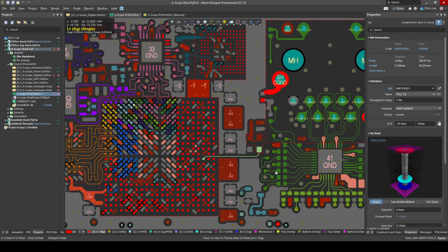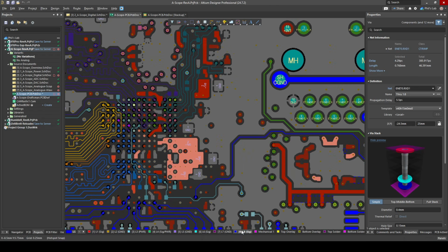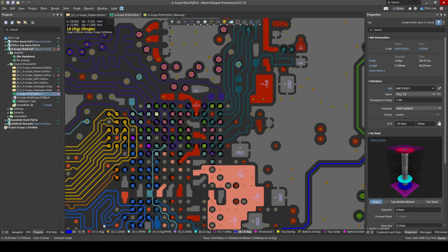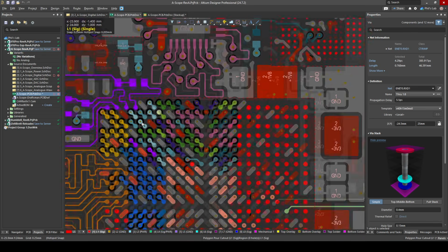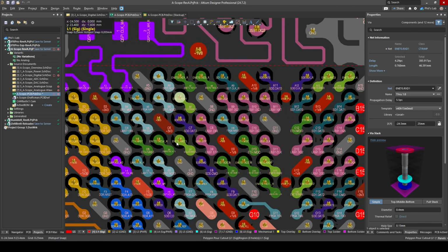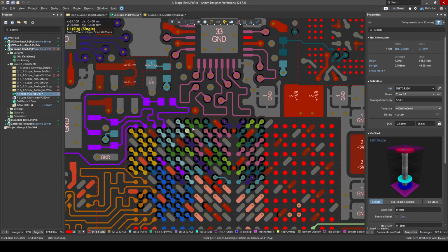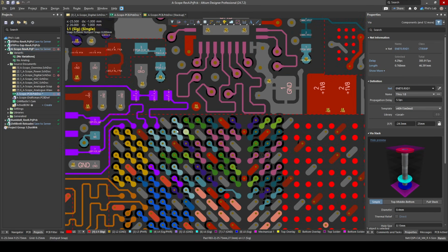Now, unfortunately, because of the constraints of this board, and because I have a lot of vias on the bottom side, loads of decoupling capacitors and other components, for the driving side, for the TX signals, which come from my MAC and go to the PHY, I can't really place my termination resistors particularly close. So this isn't particularly optimal. Ideally, your termination resistor should be as close as possible to the source side, but we will see that for the RX side and the RGMII signals.